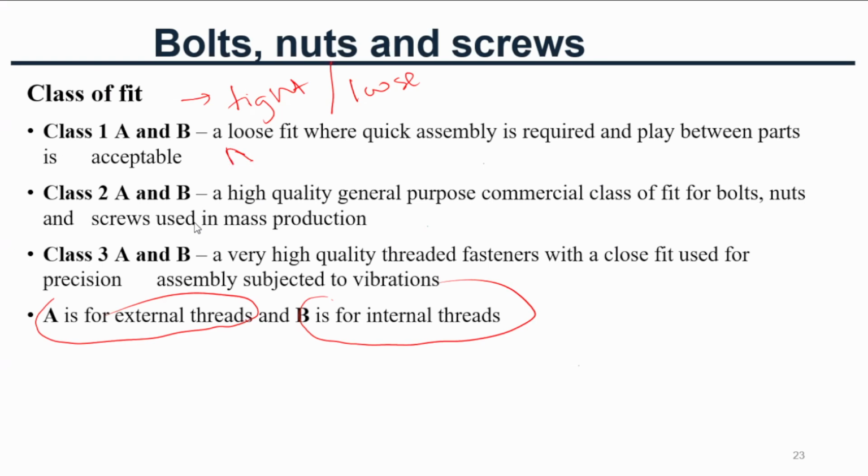So this is a loose fit where quick assembly is required and play between parts is acceptable. So use it where quick assembly and disassembly are important. So class 1A, 1B allows some small play, a small clearance between the two parts, nut and bolt.